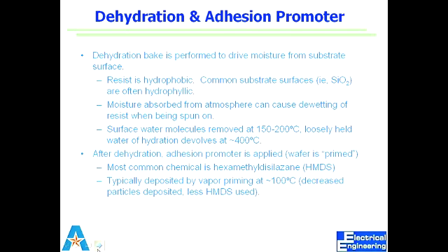What is hydrophobic? It repels water. It doesn't like water, right? What's hydrophilic? If one of them doesn't like water, the other one likes water. What's going to happen? One will try to get rid, one will try to keep water. So it wouldn't stick, right? So you want to get rid of all of the water that's there on the hydrophilic surface, so the hydrophobic resist can stick. That's why you have to do the dehydration bake.